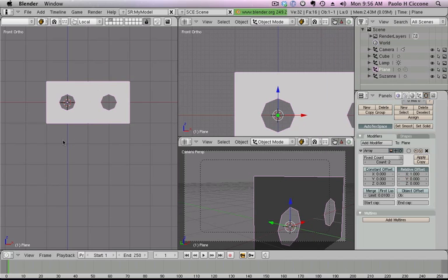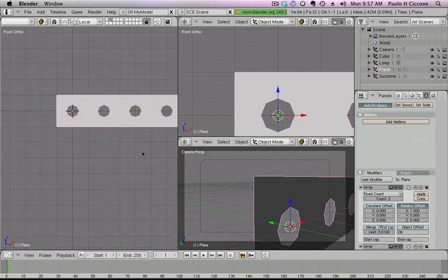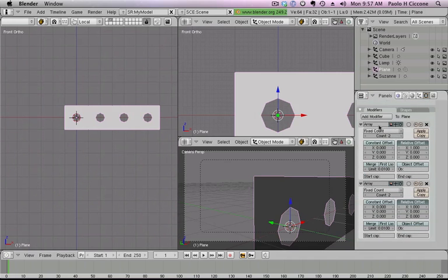There is no law in Blender that says you can have only one instance of a modifier. There is nothing like that. In fact, you can have multiple instances or multiple copies, if you want, of the same modifier. I can say, hey, I want to add a modifier, or I can copy this modifier, duplicate this modifier in the stack. Copy, and now it says, oh wow, we have 4 of those because we have an array modifier here and an array modifier here. This second modifier is a copy of the first. Not what I wanted. Well, it's easy to change.